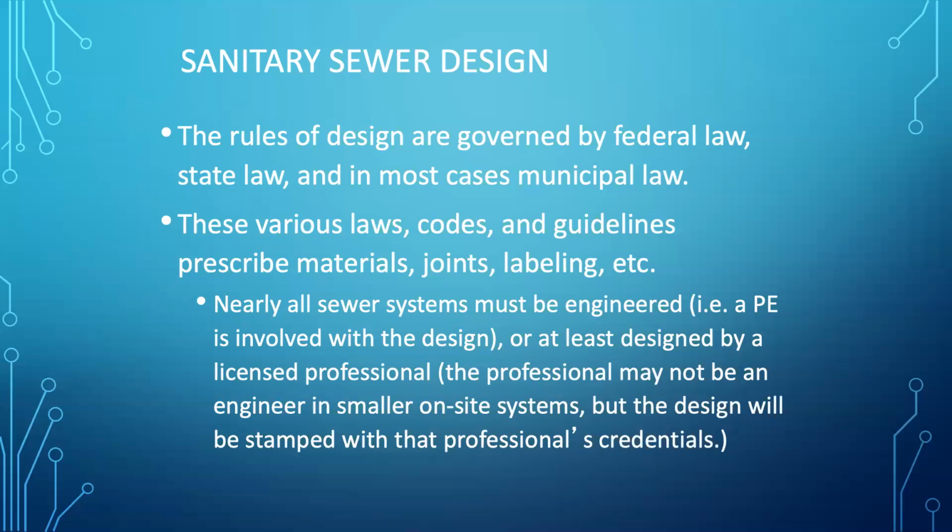The labeling, in fact, there's portions of sanitary systems that have to be correctly labeled, even if they're going to be buried underground again. It seems kind of stupid to put a label on something and then cover it up with soil, but that indeed happens, and there are prescriptions on how the labeling is to be done. And the purpose of the labeling is so that when that pipe has to be dug up again, as the contractors are digging it up, they can tell which pipe they're encountering, whether it's a pressurized water pipe, a force main, and so on.